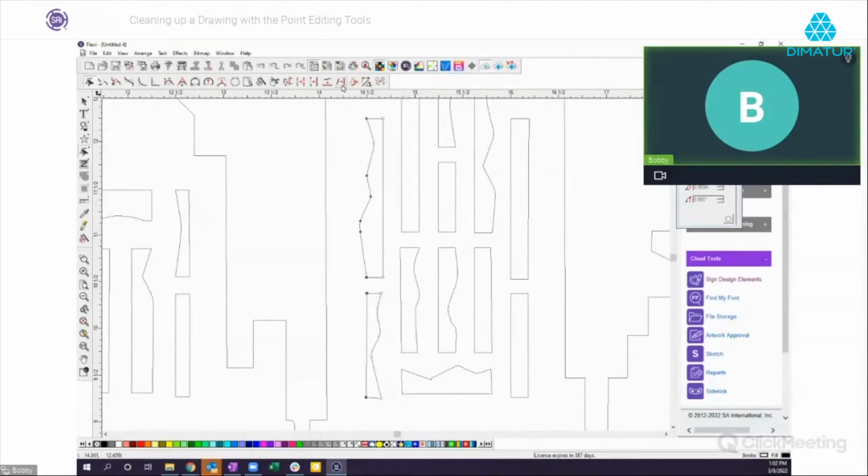So now I can click Align Vertical. And apparently I missed two points. So let's hold my shift key down and align vertical. So that's how easy it is to align points. Now it'll be a little bit easier for me to do this side since I've already done that side. Now, it aligns them based on the first point you selected. Notice it aligned everything based on this point and this point. Had I selected a point that was inside there first, it would have aligned everything based on that.